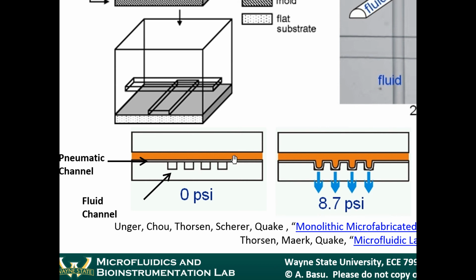When you put pressure, okay, so there's actually two inlets here. There'll be an inlet for all the liquids to go through the microfluidic chip. That will be connected to the bottom layer. There'll be a separate inlet here, which is connected to a gas input. The gas can either be switched to high pressure or to low pressure. When the gas is at high pressure, this thin region in the middle, I forgot to mention, is PDMS, but it's a thin layer of PDMS.